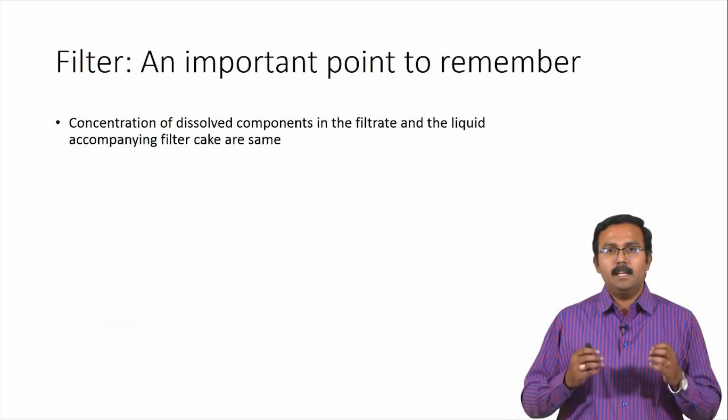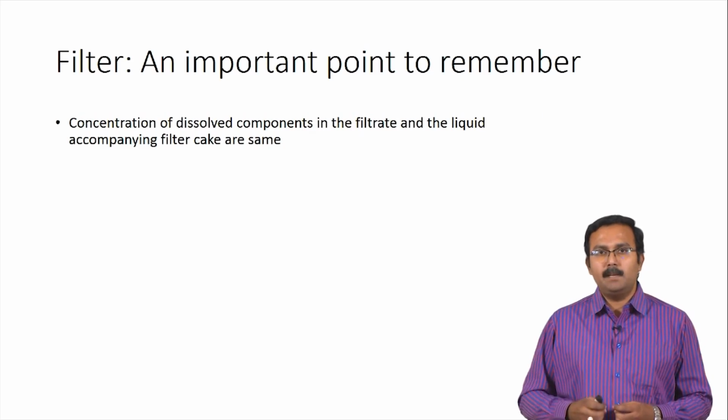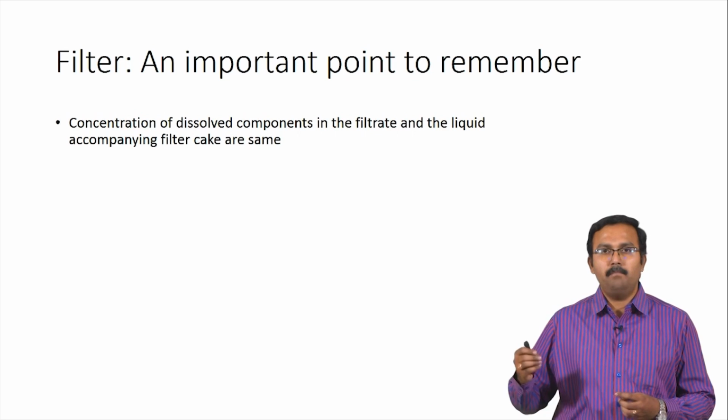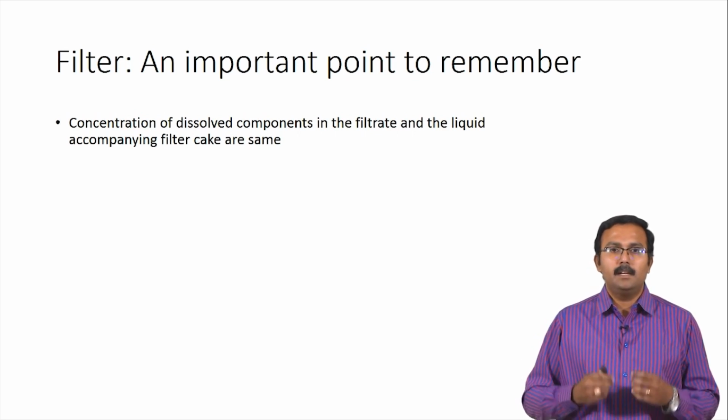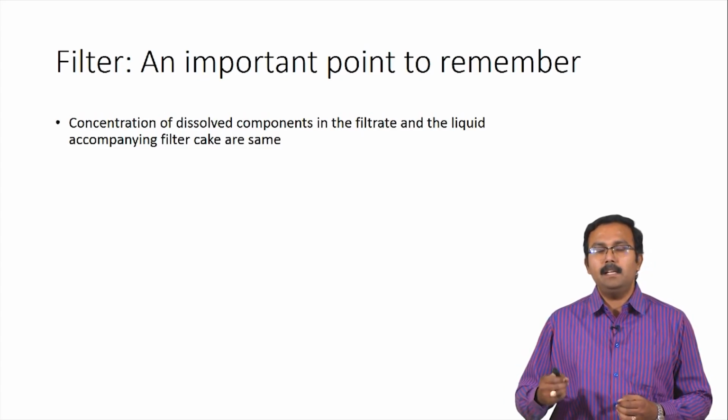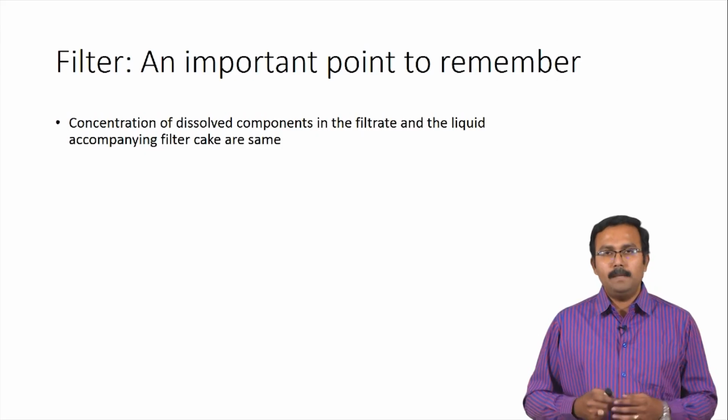Now there is an important point which needs to be remembered when we talk about a filtration process so that we can perform material balance calculations. It is that the concentration of dissolved components in the filtrate and the liquid accompanying the filter cake are the same. What do I mean by this?